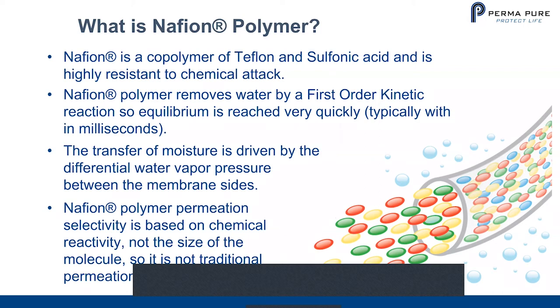Another thing that is very unique about Nafion is this process is very selective. That means only water vapor goes through in this way, and a lot of the other components that we don't want to pass through when we humidify gas streams don't, including CO2 or oxygen, other components that are in solution with the water.